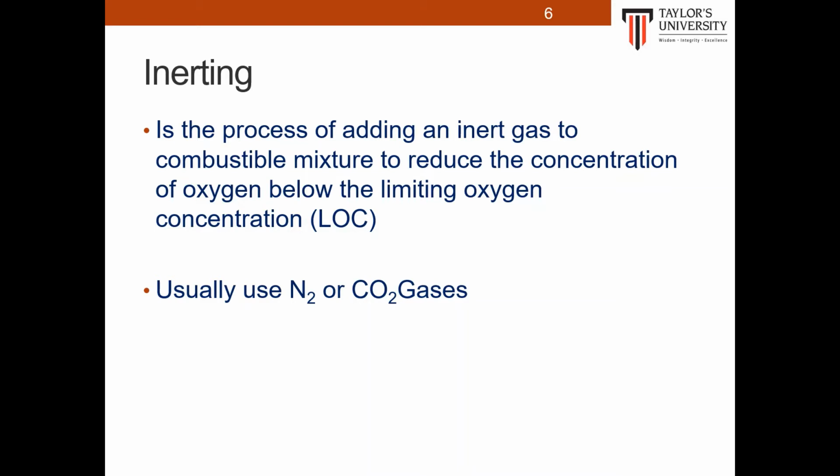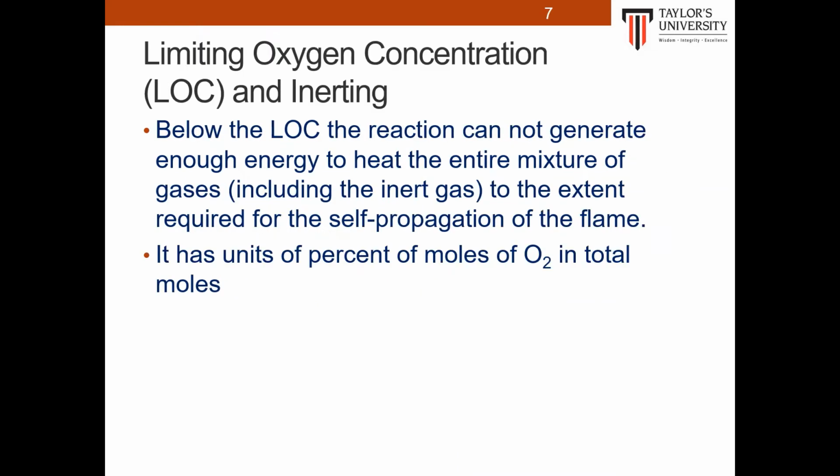There are several purging methods used to reduce the oxygen concentration to the low set point, such as vacuum purging, pressure purging, combined vacuum and pressure purging, vacuum and pressure purging with impure nitrogen, etc. Below the limiting oxygen concentration, the LOC, the reactions cannot generate enough energy to heat the entire mixture of gases, including the inert gases, to the extent required for self-propagation of the flame.